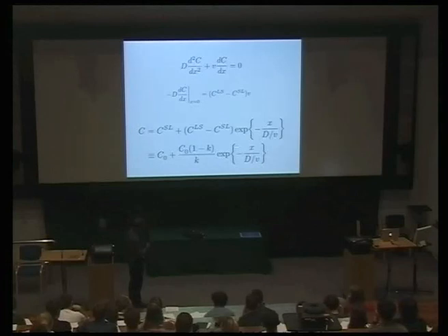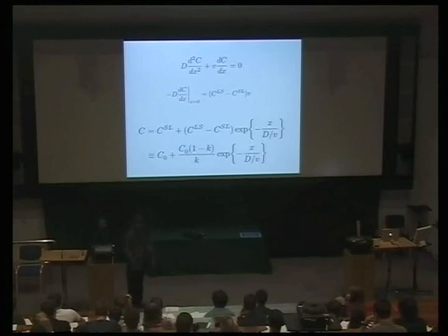And under steady state solidification, that means at the point where the equilibrium composition of the solid is C0, the velocity of the interface is given by this equation. Okay? This actually describes the concentration profile ahead of the interface, but you can rearrange it to express it as the velocity as a function of the phase diagram, and these are quantities from the phase diagram. Okay?